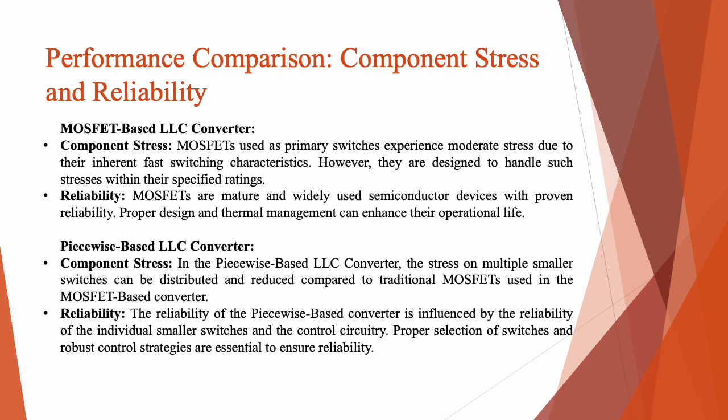Now the last one is component stress and reliability. MOSFETs used as primary switches experience moderate stress due to their inherent fast switching characteristics. However, they are designed to handle such stresses within their specified ratings. Also, MOSFETs are mature and widely used semiconductor devices with proven reliability. So their design and thermal management can enhance their operational life.